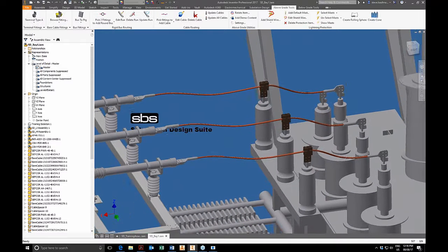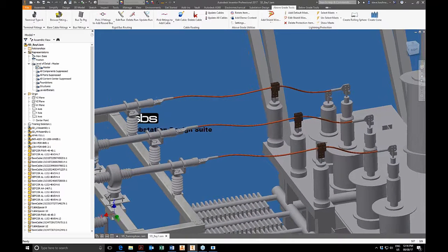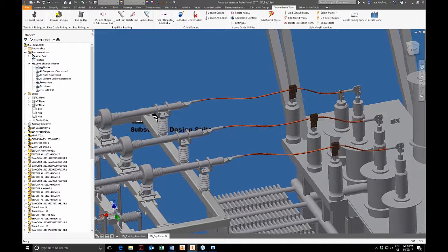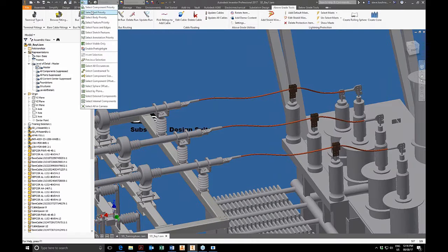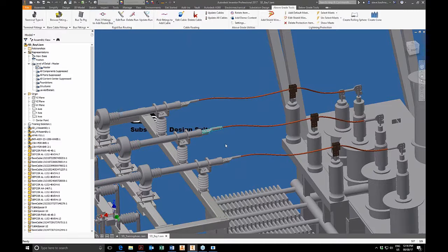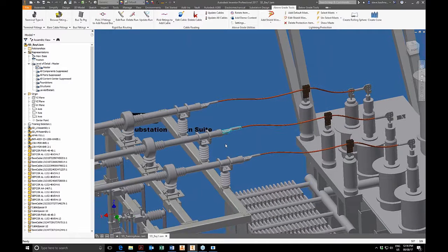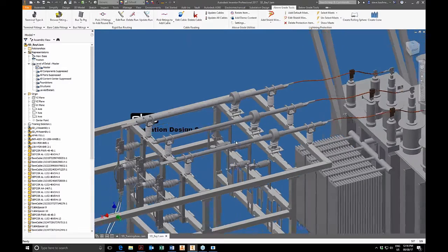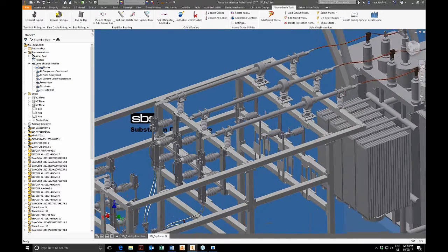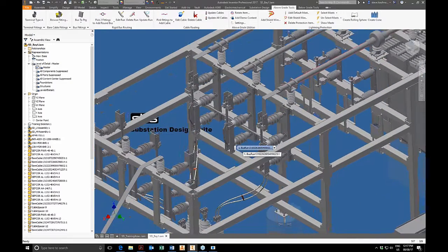And you can see the cable is placed here. It ran a little bit slow there because it's the first cable we've laid. Now that it's identified everything, it will place it in. You're responsible for putting in the right fitting for that cable size. The software does not identify the fitting to the cable size. A lot of fittings fit multiple cables, and it's difficult to identify what size you would need. But that could be a future tool to add on.